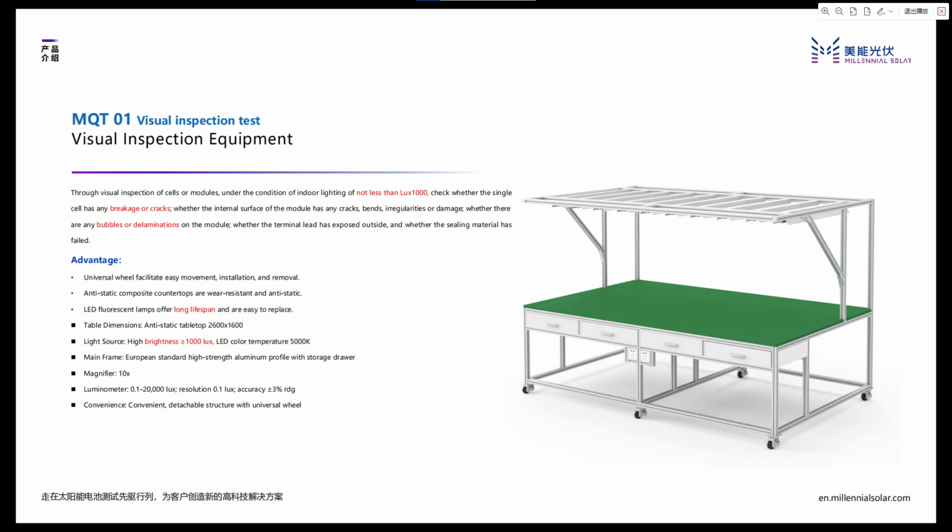So what is the visual inspection test? The visual inspection test is a visual inspection of the solar cell or module under a specific standard condition, which requires lighting of no less than 1000 lux, to check whether the cell has breakage or cracks. As for the module, you need to use these tables in this situation to check if there are bubbles or delaminations on the module, and of course the junction box as well.